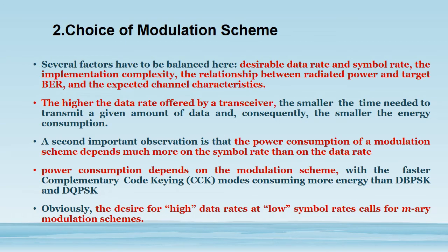Choice of modulation also plays a major role in transceiver design. The choice of modulation will depend upon the data rate, symbol rate and implementation complexity, the relationship between radiated power and the target bit error rate, and the expected channel characteristics. Based on these parameters, we have to select a proper modulation scheme.